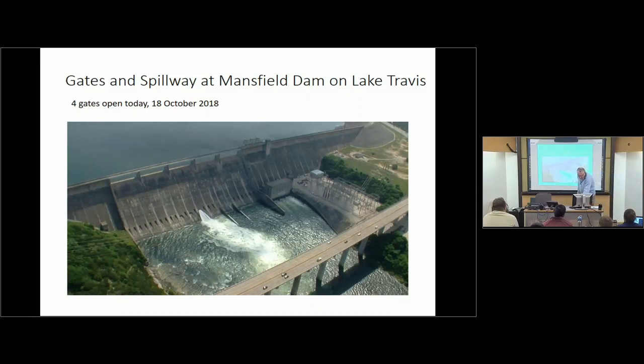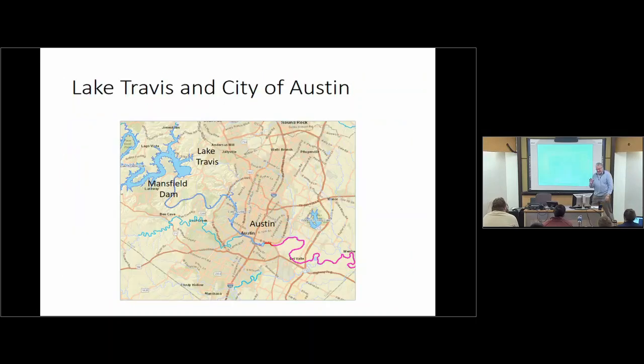So I checked the forecast. Here's Lake Travis, and this is the Mansfield Dam, which is the bottom end of Lake Travis. So all this area below Mansfield Dam is the area of concern. The purple colors that you see here are where the National Water Model picks things up again. It doesn't do forecasting on lakes because the amount of water that's coming out of the lake is actually not physical at all. It depends on how much the Lower Colorado River Authority decides to let go. So they can't forecast that. It's a human decision as to what the water is actually going to be in here.